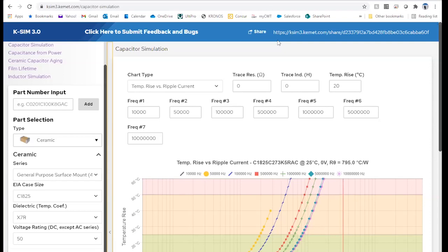I think the biggest concern probably is going to be the solderability of the device. If they're left in too high of temperatures or too high of moistures, there's going to be an issue with solderability. But in general, I think tantalum polymers are going to not really enjoy, but they're going to be okay with a little bit of moisture. It's just when the moisture becomes too high and you put it through a reflow process, that moisture could possibly build up, expand, cause internal issues. So you do want to make sure prior to reflow that the part is keeping as much moisture out as possible.